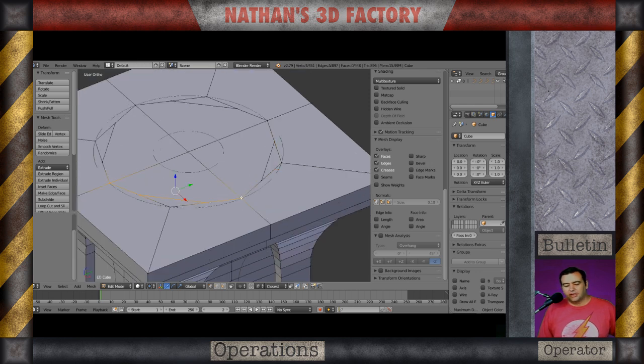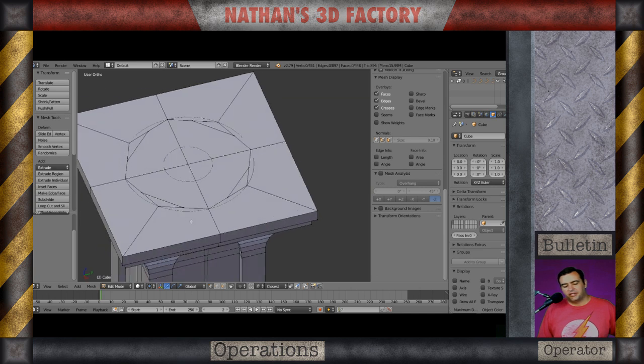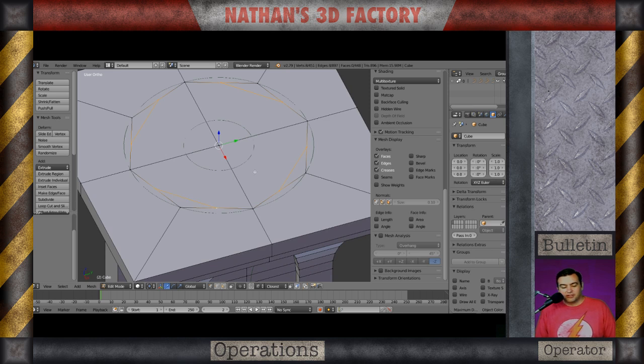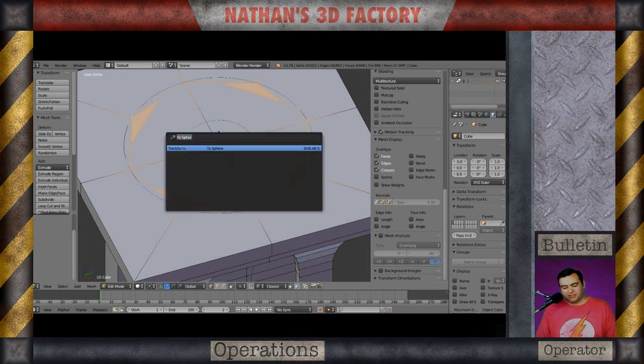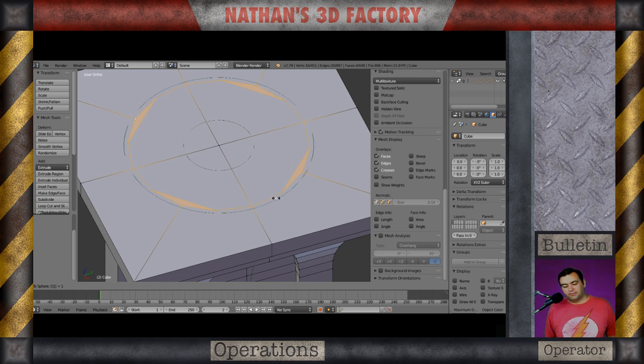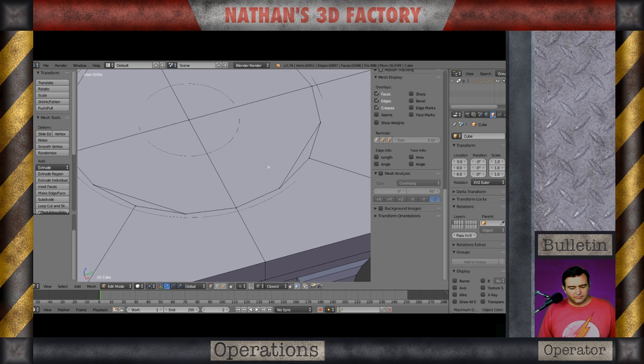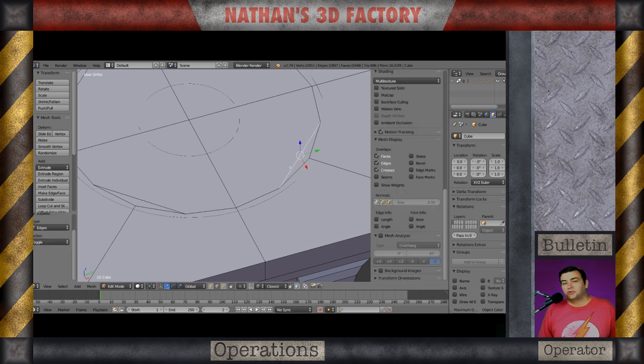So there we go. I'm going to make an inner circle as well, as you can see on the drawing once we get to that part. But right now I'm just taking care of these other things so that we have our outer circle done. I'm going to use the To Sphere command once I get that all done. Set it to 1 so it's a perfect circle as far as Blender can do it for me. To Sphere has been one of those geometric retopology tools that I've really enjoyed.